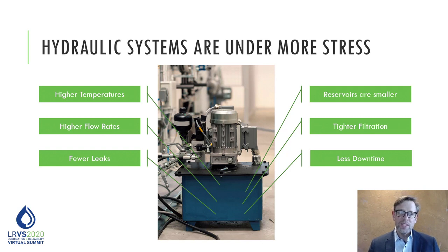Another trend that we're certainly seeing in the hydraulic market is that leaks can cause both a safety and environmental hazard. And so a lot of focus has gone into fixing leaks and having a good leak management system. Well, that's fantastic, except now you're no longer refreshing the oil on a regular basis with new oil and continuing to refresh with new additives. So now that original charge of oil is going to have to perform longer in a more stressful environment.